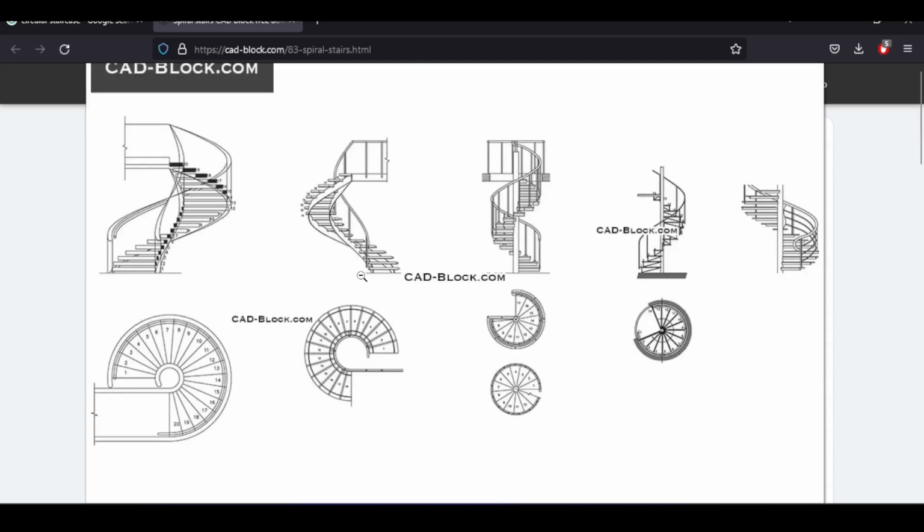So, staircases have different shapes. Most likely, they might be cantilevered staircases, which means that each individual step is carried separately and standalone as a cantilever from a central column. You could also have continuous staircases, in which case you don't have a central column, but basically the stairs carry each other.